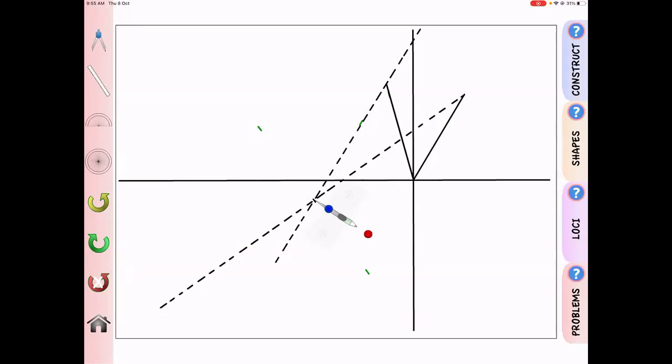we can measure the coupler now. So the coupler could be this distance minus the crank, right? This is the total distance from the center. So I can just take the center distance from O2 to B1 and subtract the crank, right? So how much is this distance? 72.